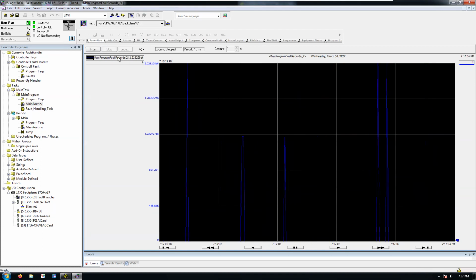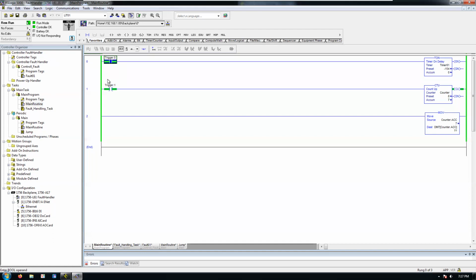How quickly these are clearing? And we've got your 2.228 E6, and this one is 1.310724 E6. So it's not really stored anywhere, and only one is true at any time. So it likely has to do with scan cycles, scan rates, and which one kind of gets picked up. So I would guess it might scan and then go back and run the fault handling routine, and maybe it comes and picks this one up and then faults.